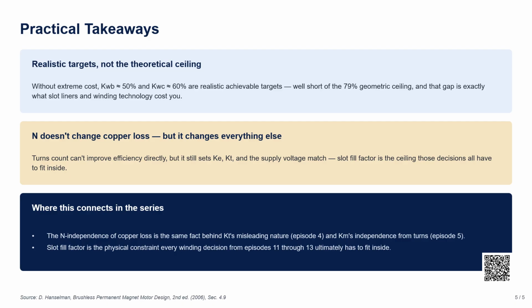Second, remember that turns count N doesn't change copper loss directly, but it still changes everything else that matters. The back EMF constant, the torque constant, and how well the motor matches your supply voltage. Slot fill factor is the hard physical ceiling. Every one of those winding decisions ultimately has to fit inside.